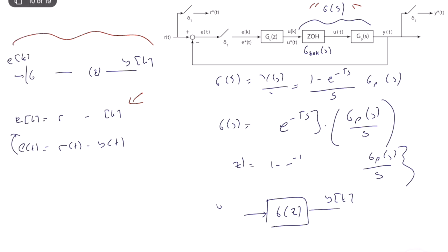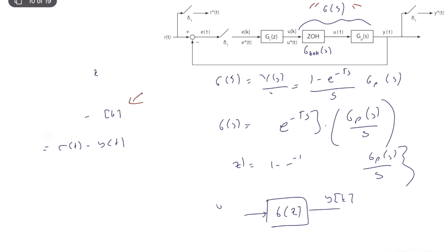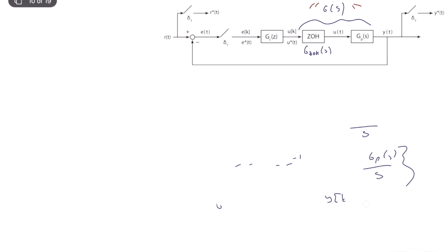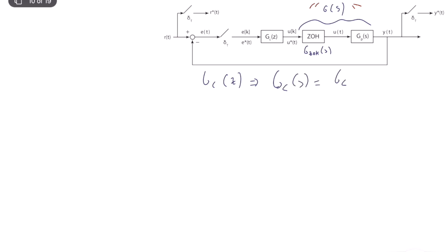Now let's analyze everything from a continuous time perspective, using the star operation instead of real sampling. So this is still G(s), there's no problem. In this case, first, we have Gc(z), a discrete time transfer function. It's a digital controller. So we will map it to Gc(s), which is equal to Gc(z), where we transform z using the mapping from z to the e domain, e to the power Ts.